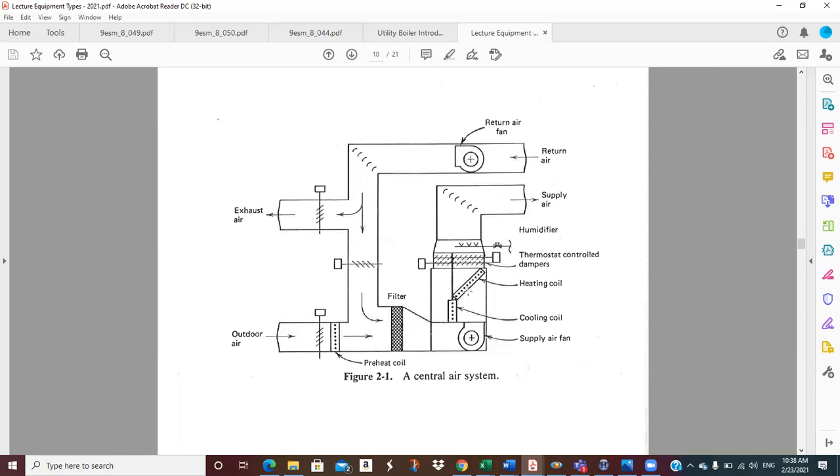So one option is to, in the summertime, just not run the heating coil, just let this be return air. Well, you don't get as good control, because if this is running the heating coil, you probably got 110 degrees here, and if you're just running return air, you probably got 80, 85 degree air here. And so when you go mixing, you don't get the same range of possible temperatures out of here. But it's cheaper. You may have uncomfortable people, but you don't have to pay as much on the utility bill. So you got to decide how you're going to operate this.